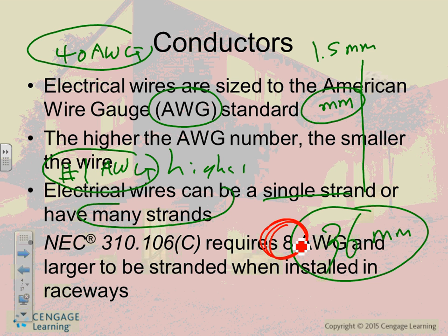If you're doing residential, typically you're using cables. If you're using cables, you don't worry about stranded. They come solid in the cables. But when you're doing conductors in a conduit, 99% of the time you will be running stranded conductors, guys. For everything else, what does the code require?